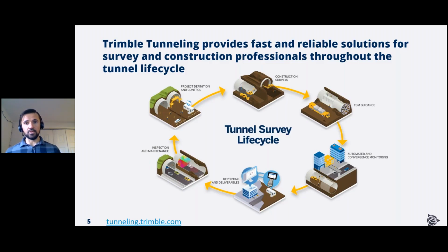And then the key component is also monitoring both above and below the tunnel. So assessing the convergence of the tunnel after it's been built and understanding how it's converging in itself, but also above the tunnel and understanding structures and important infrastructure around the construction project and seeing how that's moving relative to any work that's going on underneath.